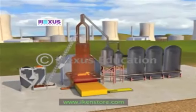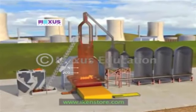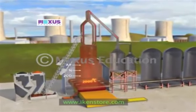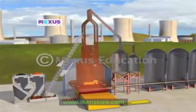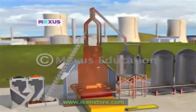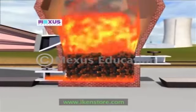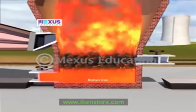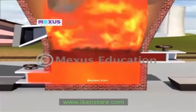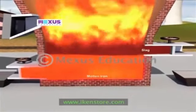This gas, together with unused carbon monoxide, nitrogen and other constituents of the air originally introduced, is let off through a pipe from the top of the furnace, and being still at a high temperature is employed to heat the stoves into which fresh air for the process is brought. As the operation proceeds, the mass in the furnace becomes molten and descends into the crucible. The iron sinks to the bottom. Impurities called the slag, being lighter, float on the top.